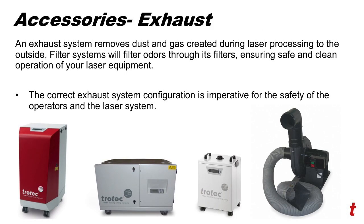All laser systems, when processing or running materials, need to be exhausted. So, if you decide to move forward with a laser system, an exhaust system is necessary when processing materials. An exhaust system removes the dust and gas that's created when the laser is processing. It can either be blown outside or filter systems can be used to ventilate and filter the materials that are being outgassed from the surface during the engraving process, ensuring a safe and clean operation for your laser equipment and operators. The correct exhaust system configuration is imperative for the safety of operators with a laser system.